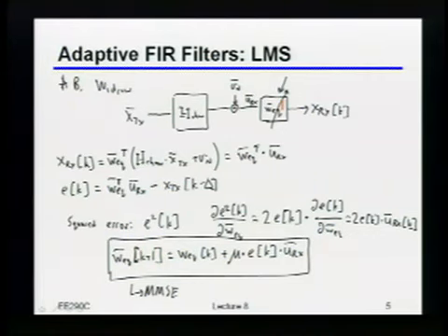If I'm making the right decisions, then I do know what my own data should be. Now, by the way, in this particular algorithm, if I really do it this way, I don't actually have to know what the data is. I just have to tap off at this point and measure the correlation between that and my received analog signal. So I don't explicitly have to know what the transmit bits were. I just have to measure the correlation between the input of the equalizer and the output of the equalizer.